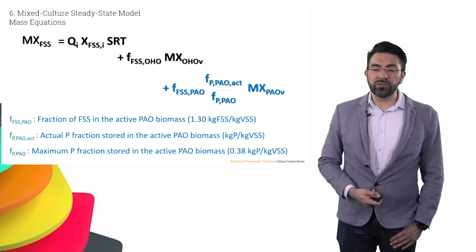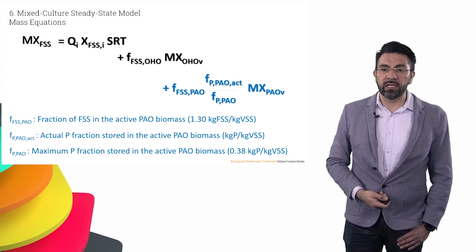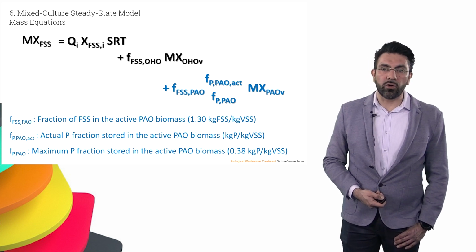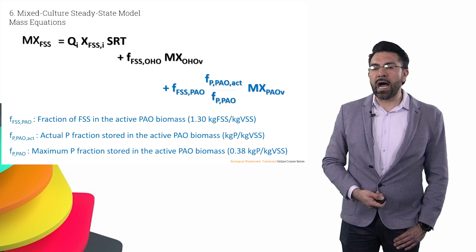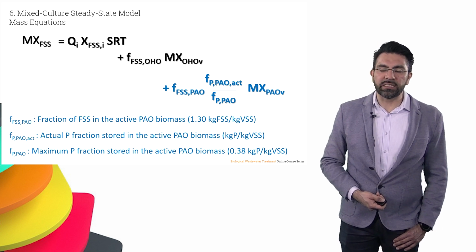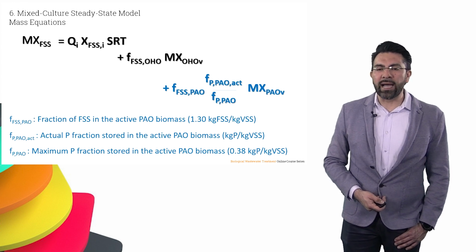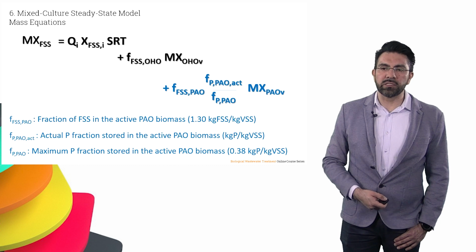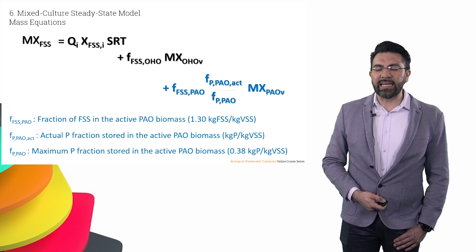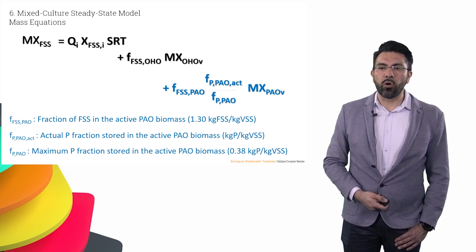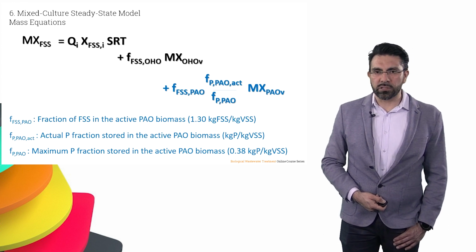This phosphorus, in particular the polyphosphate, is an inorganic compound composed of chains of orthophosphates, but these elements are stabilized, or they have certain ligands stabilized, with magnesium, potassium, and some other minerals. And that is why when the system starts to run and they accumulate the polyphosphates, we are going to see an increase in the amount of fixed suspended solids that the total masses will have compared to other systems that do not perform the EBPR process.